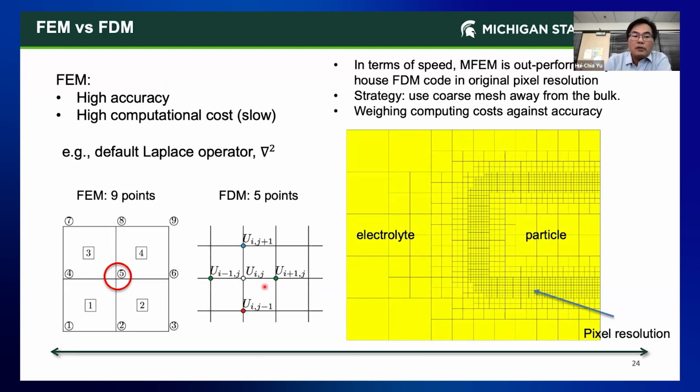By comparison, you can see that in evaluating the Laplace operator, FEM is already twice as much calculation. And if you are doing 3D, you use 27 points versus 7 points in finite difference. And in the M matrix, the mass matrix, you will do the same thing. So FEM is high cost, but it's very high accuracy.